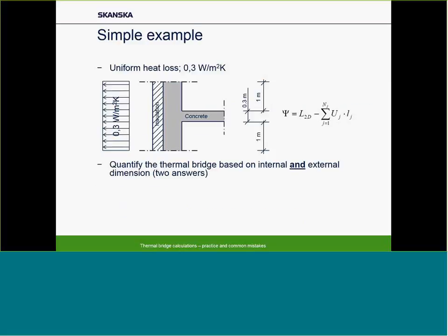I don't only work at the company called SKANSKA, I also lecture at Lund University. And this is a standard, simple example I always give them to be able to understand how to grasp the concept of thermal bridges, which I believe is very important. They always first have to start with discussing in group if this is an actual thermal bridge, only seeing this kind of picture. And then they get the equation, as you can see out to the right, and then they get the task to quantify the thermal bridge based on internal and external dimensions.